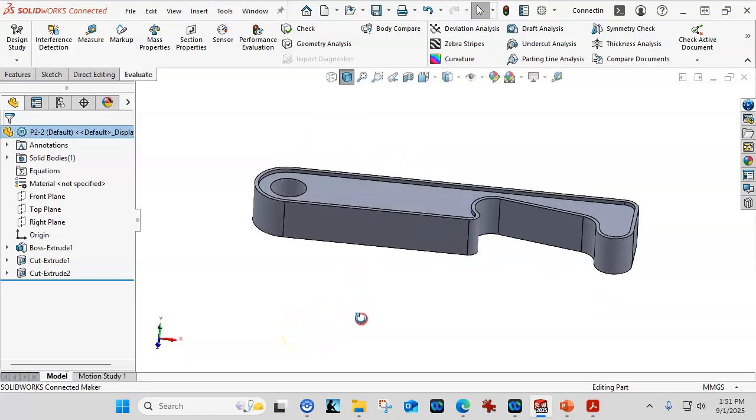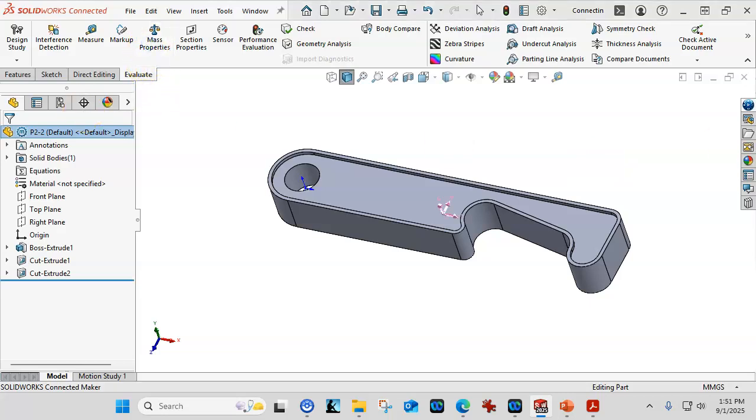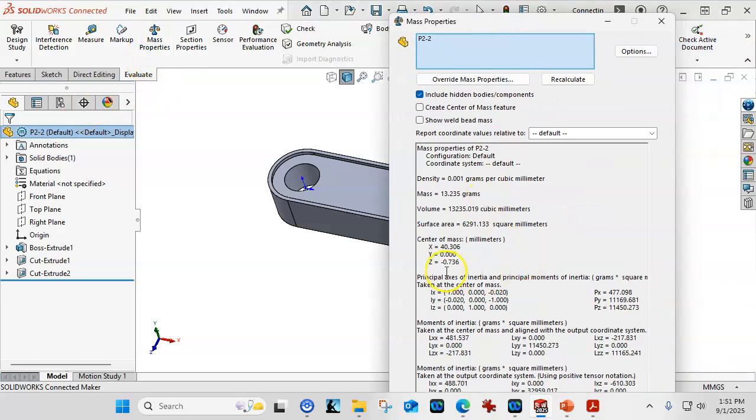Again, the mid plane. Let's take a look at that real quick before I finish. Going mid plane and isometric, the geometry. I'm trying to see if the isometric view had a better, but it's not really going to affect our volume. But the center of mass would change if I wasn't exactly in the right location. But again, going from the front plane to the top plane, the x and z values would probably shift for the center of mass. All right, we'll finish this one up here.